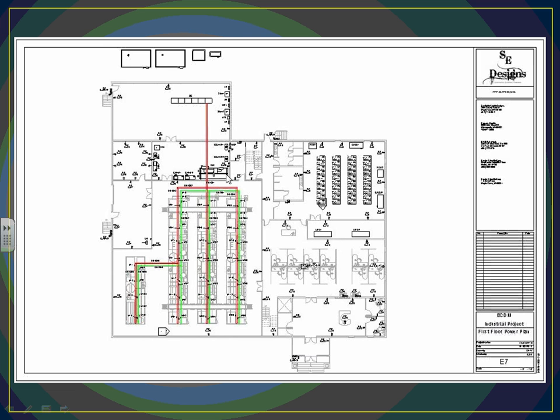There are two voltages. Okay, so we're going to be sizing the bus duct, the 480/277, as well as the green, which is the 208/120 bus duct. In here, there's a couple of transformers and a couple of panels to feed the building. I'll show you the riser, just to give you an idea. So a couple of generators in the back.